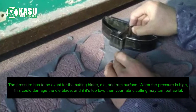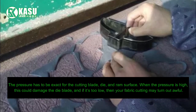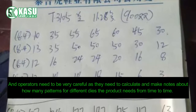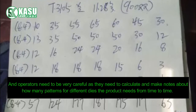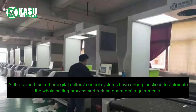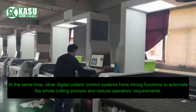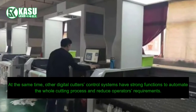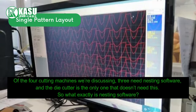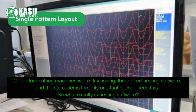When the pressure is high, this could damage the die blade, and if it's too low, then your fabric cutting may turn out awful. And operators need to be very careful, as they need to calculate and make notes about how many patterns for different dies the product needs from time to time. At the same time, other digital cutters' control systems have strong functions to automate the whole cutting process and reduce operators' requirements.